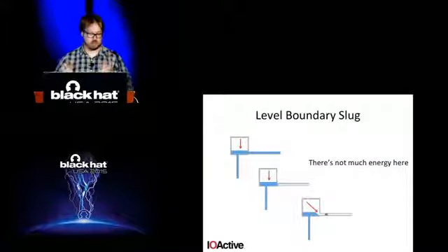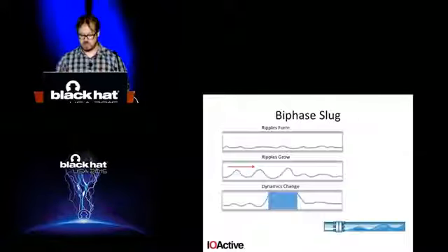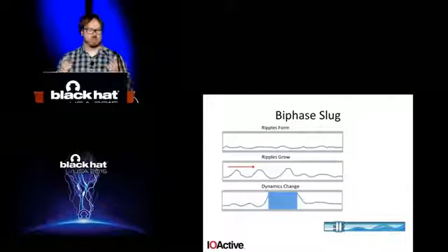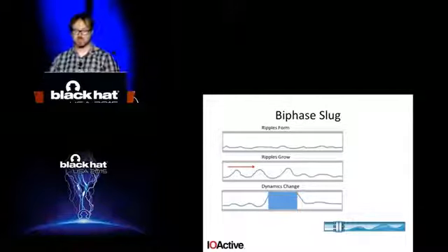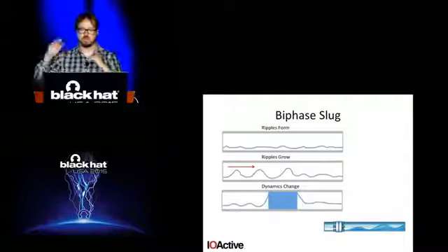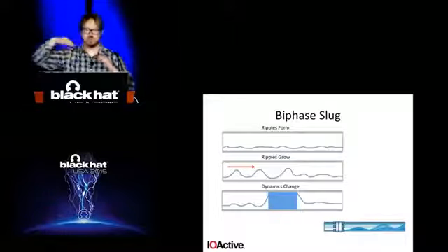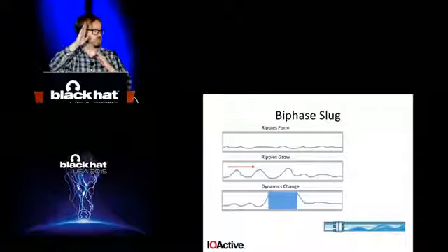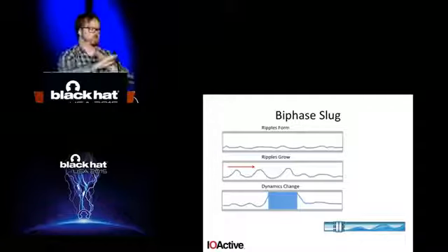Besides water hammers, you also have cases where pipes are meant to carry liquids, but interesting things happen when pipes carry liquids and gases. So if you have a pipe carrying liquids and gases, and the gas is moving at a different speed than the liquid, as the gas flows over the liquid, it'll form little ripples in the liquid, and the ripples get bigger and bigger until they touch the top of the pipe. Once they touch the top of the pipe, they form a seal, and they take the water and push it through the pipe really fast as all the pressure builds up behind it.